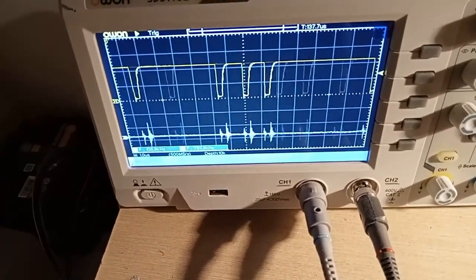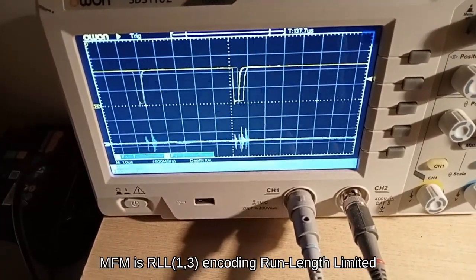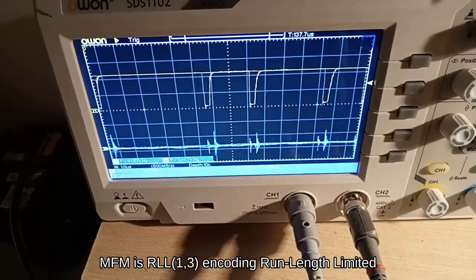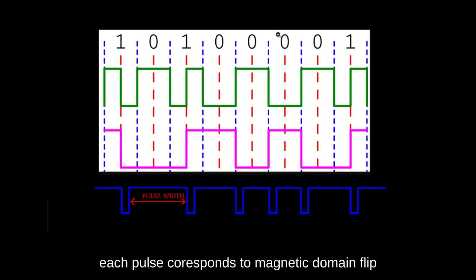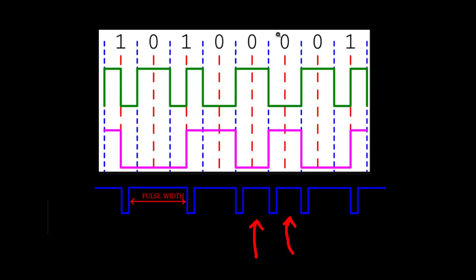Data in tracks is stored using modified frequency modulation, MFM, at a frequency around 500 kHz. MFM encoding uses 3 pulse lengths to encode MFM bits. A short pulse produces 10 MFM bits. A medium pulse produces 100. A long pulse produces 1000.